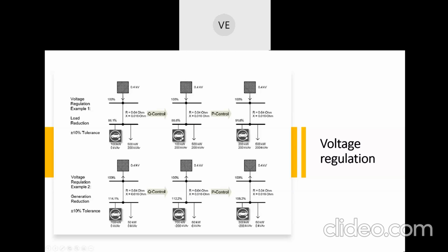Now active power control. So now it is only 100 kilowatts. Discharging electric vehicles contribute 100 kilowatts generation. Now we are increasing it to 200 kilowatts generation. So it is now well within the limits. 91.8% is the profile, that is, 0.918 is the per unit value of the local node voltage. So it is within the limits. This flexibility is used here for voltage regulation. This can be another ancillary service which is charged. That also is an avenue for earning.